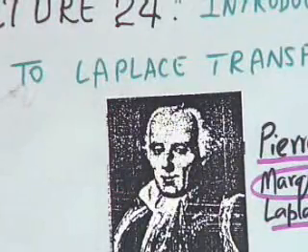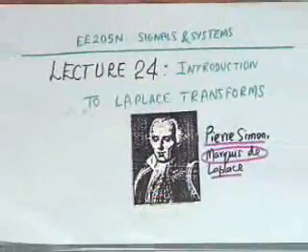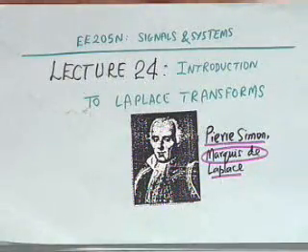He is credited with the transform that bears his name, Laplace transform, which has revolutionized the analysis of circuits and systems with non-sinusoidal inputs. With sinusoidal inputs, Fourier transform does a wonderful job. You can even avoid Fourier transform. You can go to phasors and carry out the job. But Laplace transform is the most general tool known for analyzing linear time invariant continuous time systems. This I must point out. This is not a transform for discrete time systems.